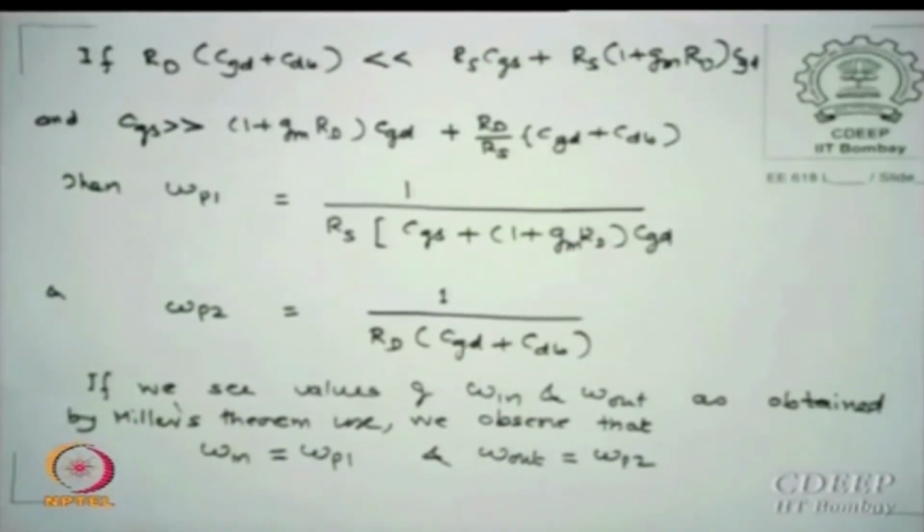And therefore in many cases using Miller, the values are good enough. Like, let us say if the cutoff is 4 megahertz, we are overestimating it as 4.5 megahertz. That is all that will happen if you do not use accuracy.